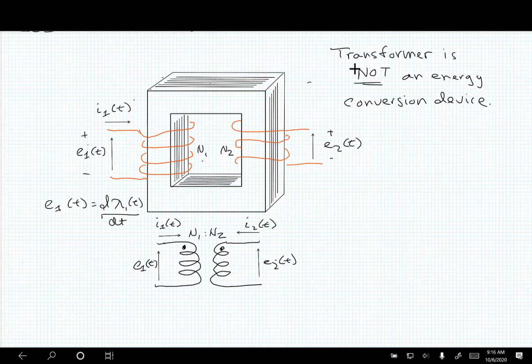Okay. So we have this. Now, if I were to say that the current is pointing into the dot in this electrical schematic, that's the same thing as saying that the MMF from the secondary side is contributing to the flux that's flowing in the core. So let me explain what I mean by that. Let's apply the right-hand rule to the coil. I'll draw my cartoon hand here.